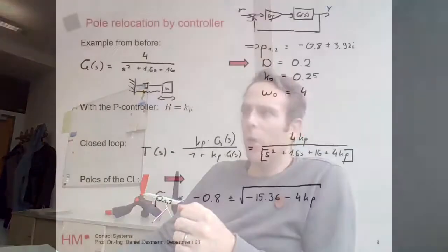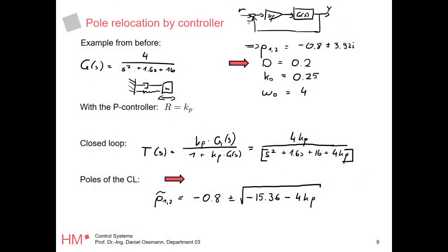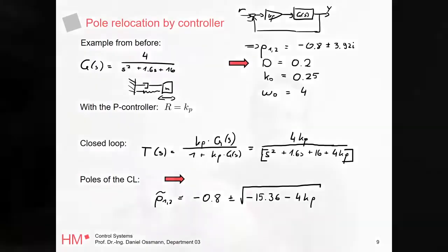So we exclude 0. Why don't we put in negative numbers? Well, we always say we have a negative sign here. We want to have the control error multiplied by a certain gain. If you now basically say Kp can be negative, you're changing that sign to a plus here. So you're changing the sign from plus minus to minus plus. You're basically further destabilizing your system. So we're not going to do this.